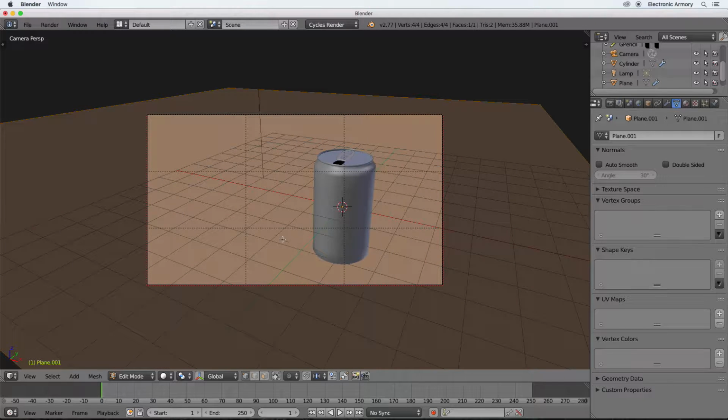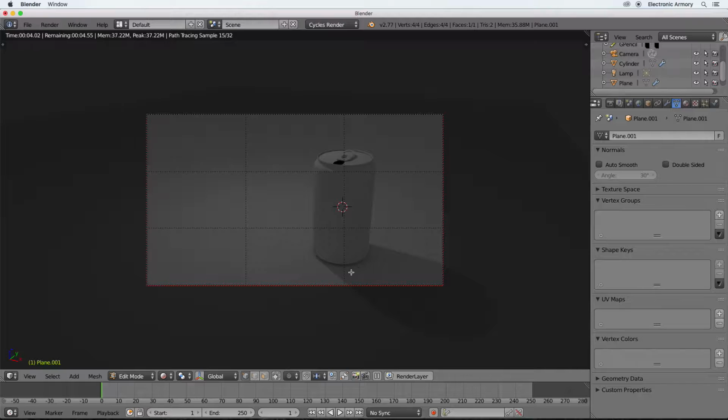And what I want to do is render this view here. And what Cycles will do is it'll render it as quickly as it can and then add different samples. So as I wait, it gets better and better and better. This is a little fuzzier than our final render. But what's nice about this is we can see this render in real time. And actually, let me undo that because I don't want to move my camera. So as I move that around, it's re-rendering.